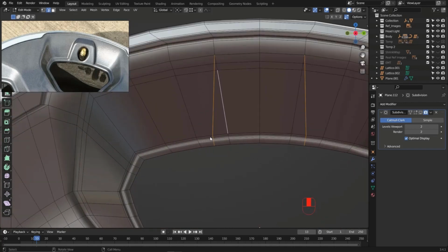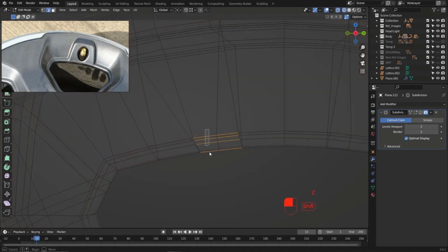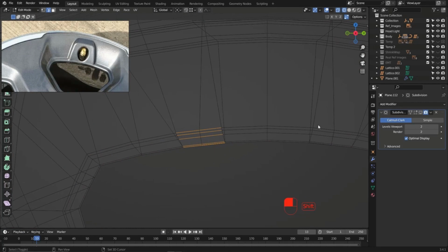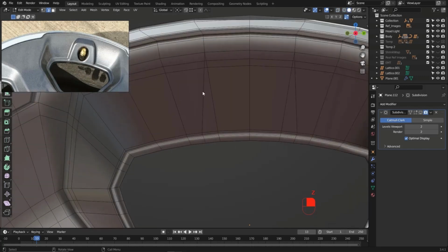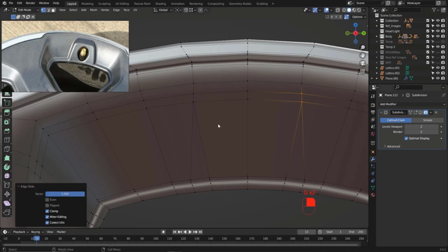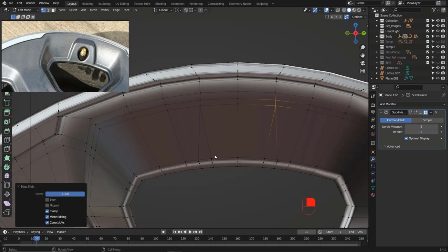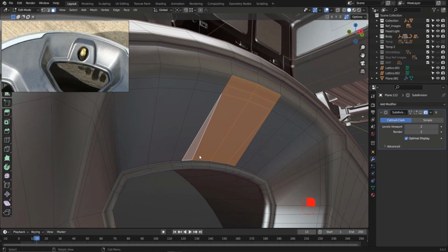If you want to put these lines exactly in the middle, just grab these edges in the wireframe mode and select those as well. And then hit right click and choose Space. And now it's done. Now it's in the middle. Alright, now what else? Now I think we can grab these vertices and hit K twice and merge those over here and those over here. And go to the face mode and let's select these faces. And I think we should...